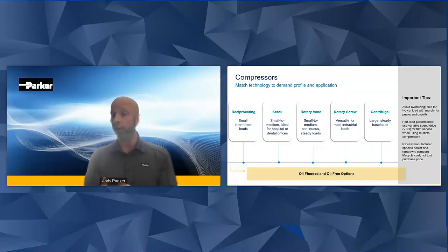Consider having a variable speed drive in your system. That motor is actually designed to meet the optimal air demand. That will contribute to significant energy savings, but also note you only want one VSD in your system. If you have multiple ones, they're going to fight. Even with good controls, they're going to fight to see which comes on first.